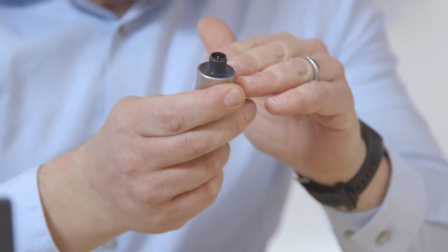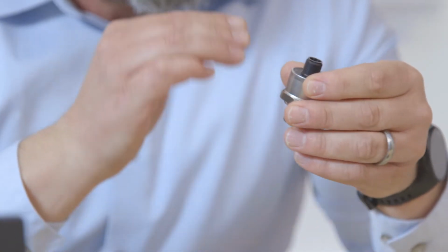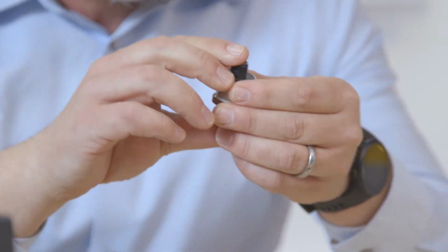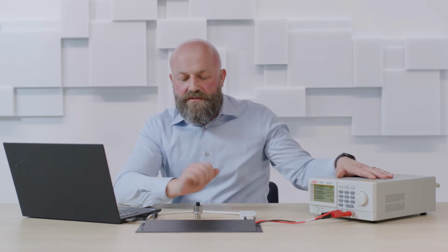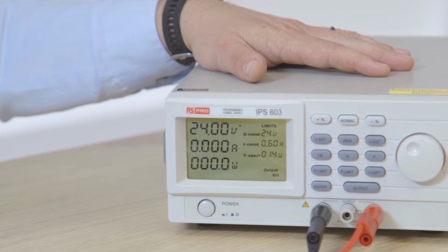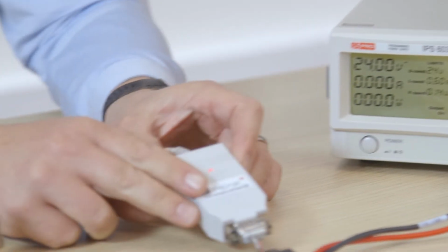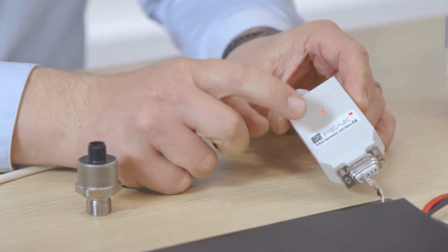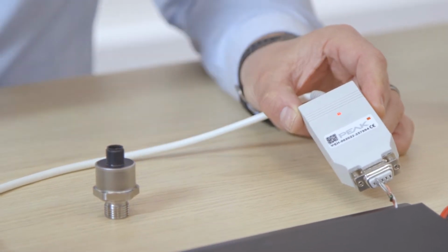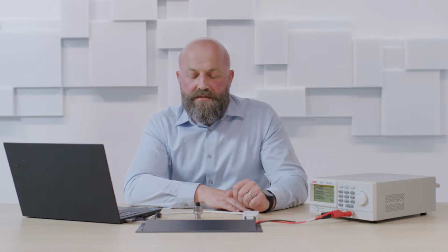various industrial applications. And the communication module I'm here to talk about today is a CAN bus, and more specifically, a CANopen protocol embedded in the sensor. To illustrate this, I will use a little equipment here, as you can see. So a power supply to power up the sensor to the needed voltage level, of course. I have a communication tool here, which in this case is from Peak. But this could basically be any CANopen communication tool available on the market.